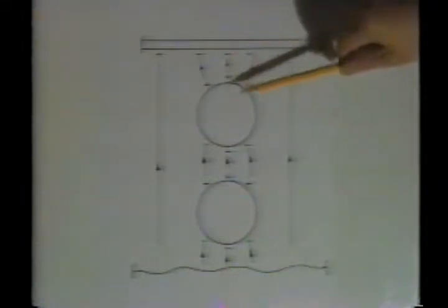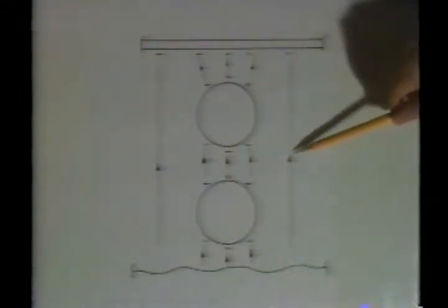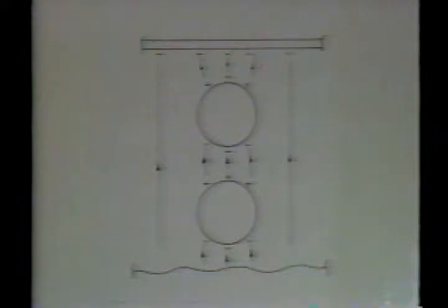We're going to measure the effective permittivity by measuring the change in capacitance as the array is placed between the plates of this plane parallel plate capacitor. The cage is grounded for shielding and to keep us from touching the bottom electrode.